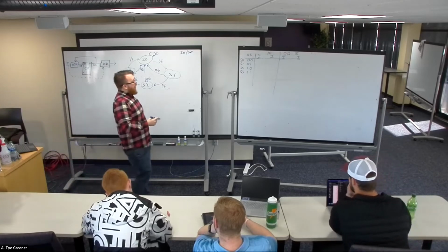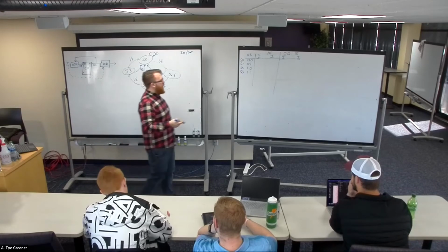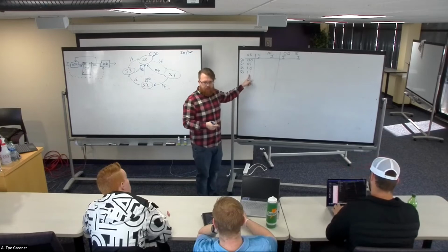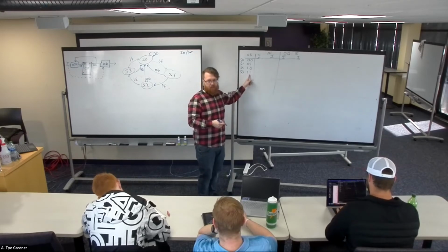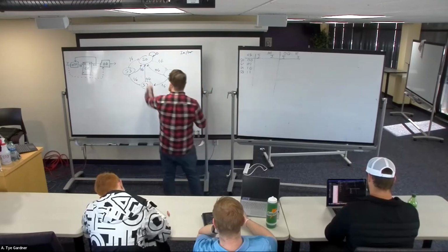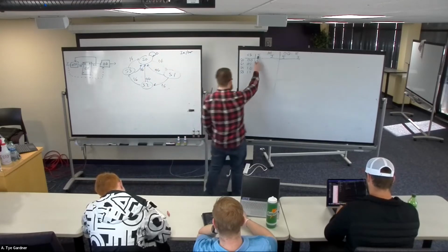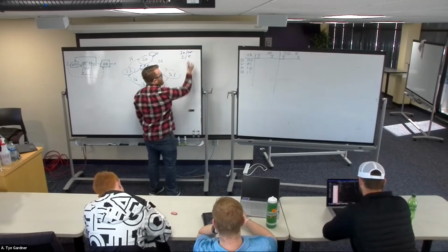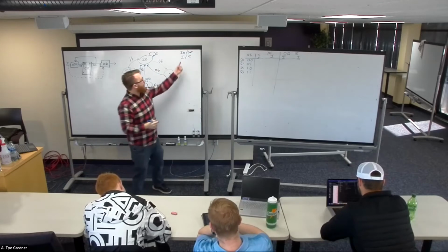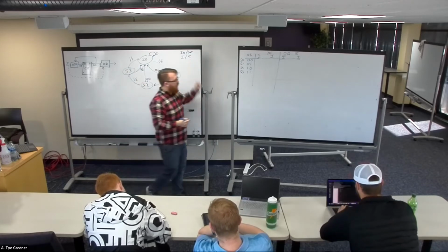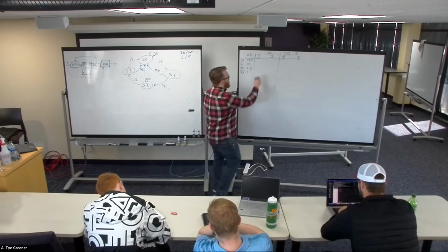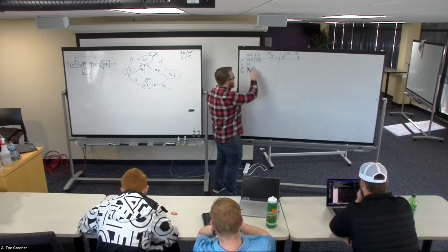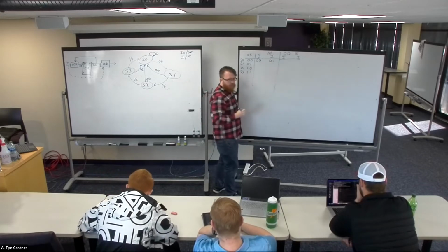Then we can either start labeling them as S0, S1, or we can skip to the codes. So this is a state name, this is the state code. If I look at the code, I just look at state 0, and if I get a 0, in other words not I, right? Because in the case of in/out, it's I/Z. So my input is I, my output is Z. Then we would say, if I have not I, stay in the same state. And if I do get I, transition to state 1, which I've called state 0, 1.